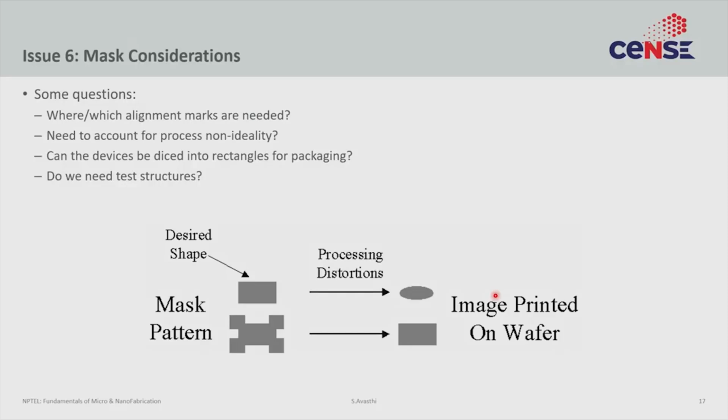So if you have them on your mask structures already, then it becomes very easy to fine tune the recipe, figure out what went wrong, fix it and move on. Otherwise it's a black box. You started with a wafer, you ended up with a device not working, which process failed, very hard to find out. So fix that at the mask layer itself, right?